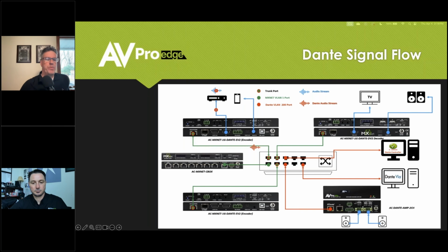Actually, they're not. All of our MXnet devices are set to 1080p as default out of the box. It's like the other matrix switches too. They all come with a 1080p EDID, so whatever you plug into it's going to be okay. The reason for that is it's set to the lowest common denominator, so you're going to get a picture out right away, no matter what, basically. As long as your wiring is good and your wiring works, you will get a picture. From there, and set up through Mentor, you can switch that very, very quickly with a couple of mouse clicks, and yeah, you can set it for pass-through, which is what I suggest in some situations.